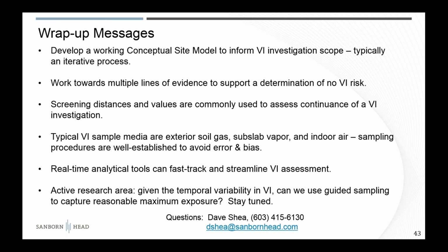My personal experience is I haven't had failures of SSD systems, but at the same time, we're also at least doing annual checks of the operation, the pressure field extension, the fan. So walking away from these is not what I would recommend. I think you have to have at least some monitoring and maintenance program. That doesn't mean you have to do sampling, but this is an engineering control, and engineering controls, particularly if they're mechanical, they can fail. So checking on that mechanical reliability is a good idea.